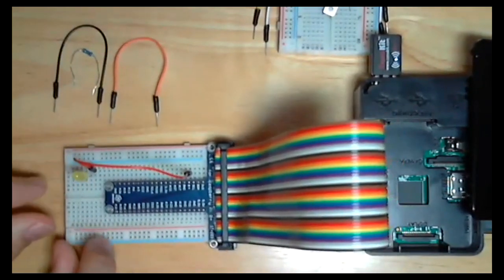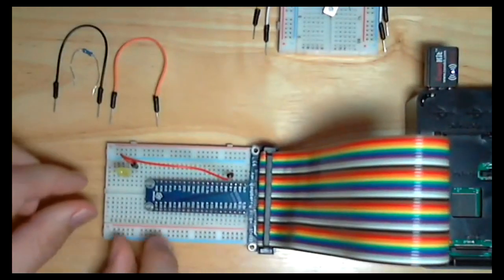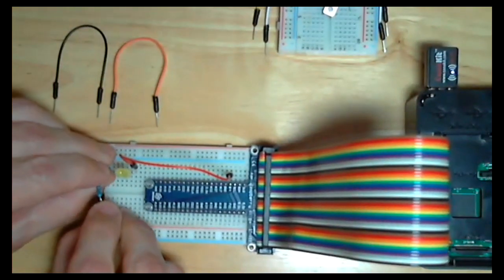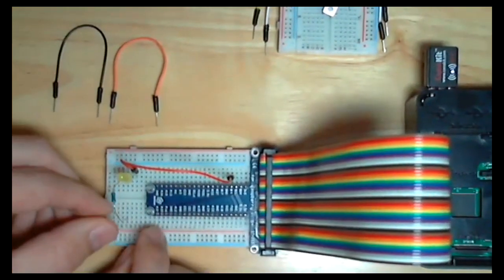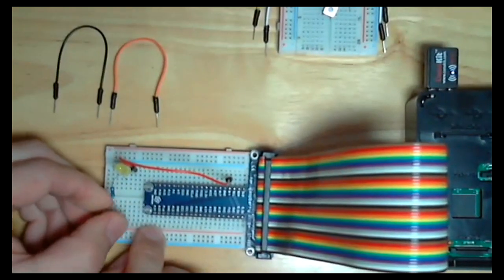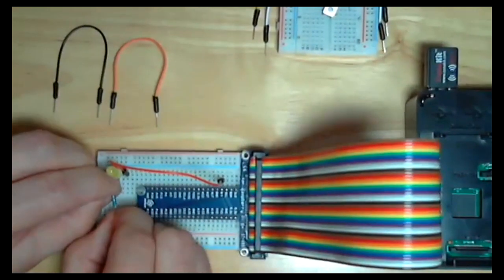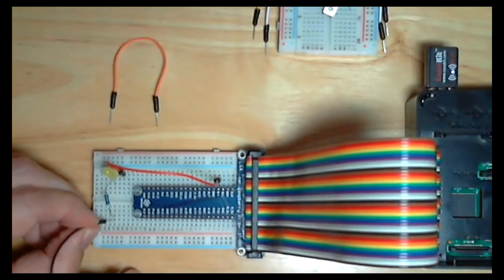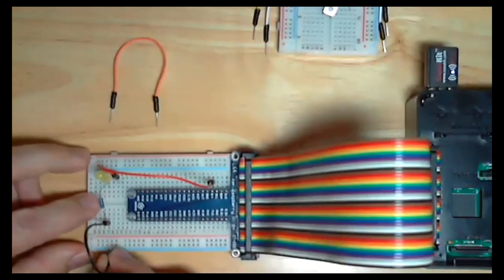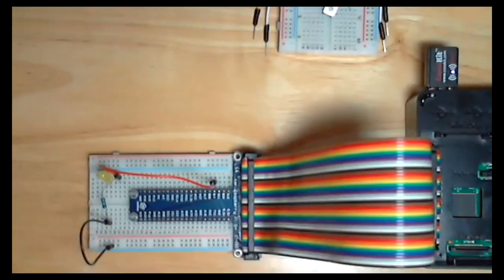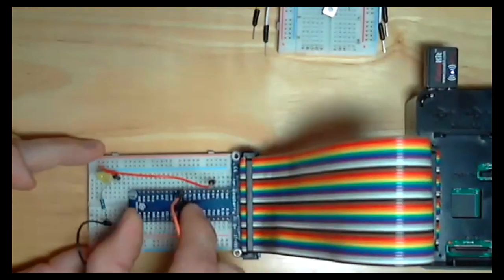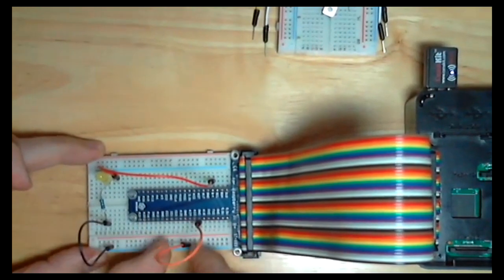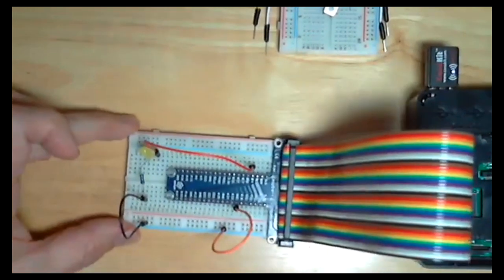All right, so I've got to slide this stuff over more. So I got the LED plugged in there. Now we just need to take a little resistor. Make sure I push these things down enough. And at this point, we're running everything to ground. So I'm just going to connect to the ground section of the breadboard. And then I can wire this over here to a ground pin. Doesn't really matter which one I choose. So that's my little rinky-dink circuit.